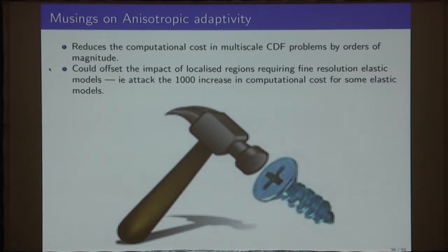And I think the reason it could be of interest here is that for solving the elastic wave equation, there are going to be localized regions where you're incurring all of your cost. So this could be an opportunity to adapt the mesh around that area, and maybe even have subcycling in your time step in that region. So suddenly it doesn't dominate your total cost.